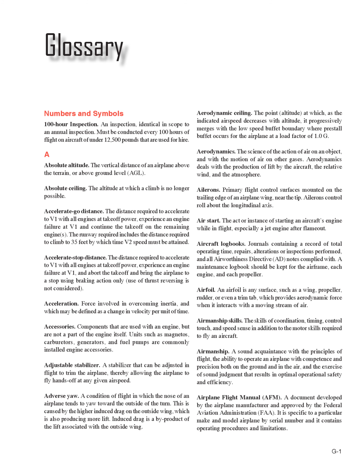Glossary. Numbers and symbols. 100-hour inspection. An inspection, identical in scope to an annual inspection, must be conducted every 100 hours of flight on aircraft of under 12,500 pounds that are used for hire.